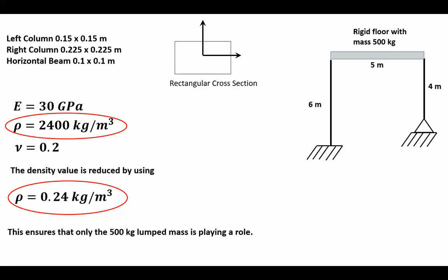However, there I created my geometry as a two-dimensional sketch, and then I had to join it so that the entire structure, which is just two vertical columns and a horizontal beam, were meshed at the same time. And therefore, there were no duplicate nodes at the junction between a column and the beam, because they were joined. Not everybody does this, so what I'm going to do is repeat the same problem.